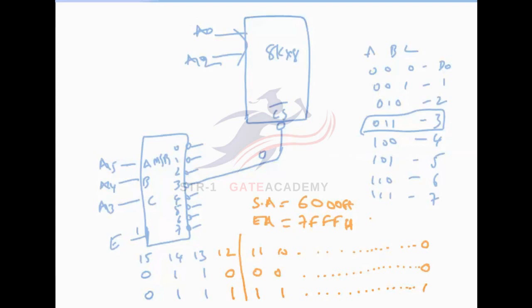So in this memory interfacing, always we have to remember this chip select bar should be 0. This device is any device, any gate we can use here, either decoder, NAND gate, NOR gate, any type of gates. Output we want always 0 here. Okay, from the given circuit diagram, find out the input combinations. With those input combinations, our output should be 0. Then the memory is activated. Right? So this is the procedure to find the starting and the ending address locations of the memory.